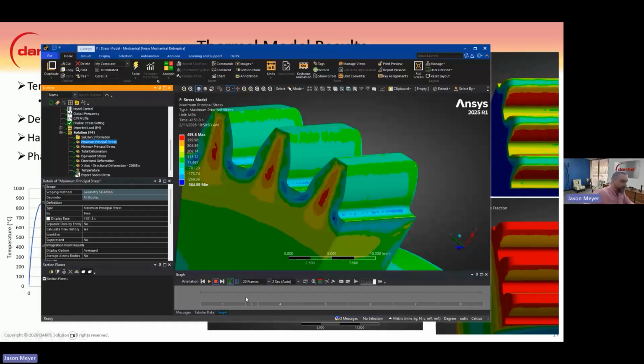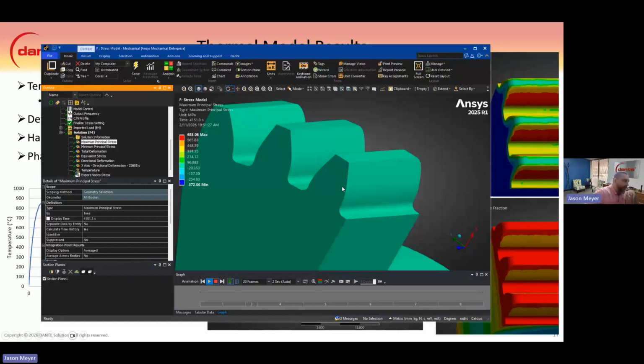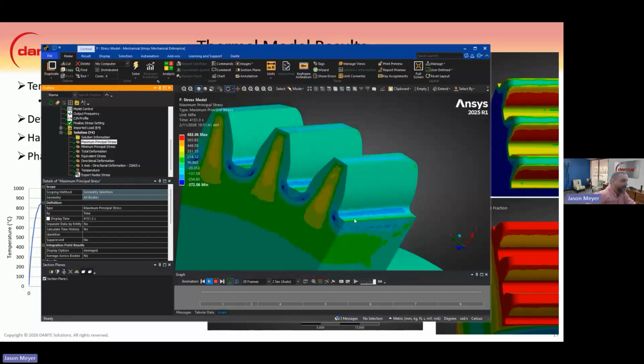We can also animate this and show the process as it happens. We can see that during the martensite transformation, that's when the tensile region starts to form here. Apparently, this is a little bit advanced right now for Teams and my systems. It's having a hard time running for the stresses as well. We can also do deformation. Oh, here we go. We can see the martensite transformation there. And then in a few seconds, it'll even out. Again, we can also look at deformation.